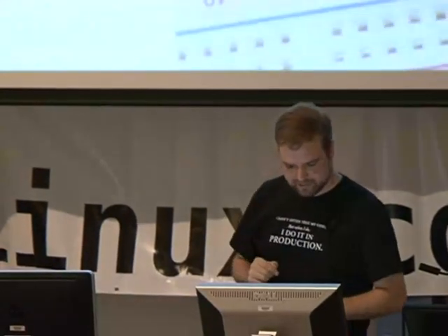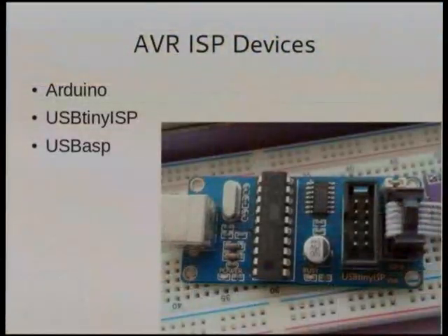And it's the little 2x3 header that you see on a lot of the breakout boards. So you get something like that, USB on one side, and the SPI on the other side, and it lets you actually rewrite the flash in the Arduino clone that you're building without having to have a serial upload mechanism or a bootloader already on that chip.